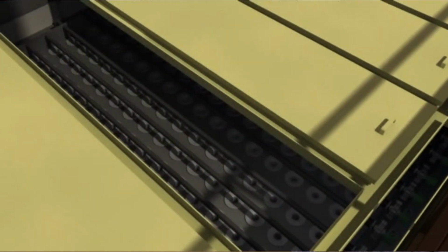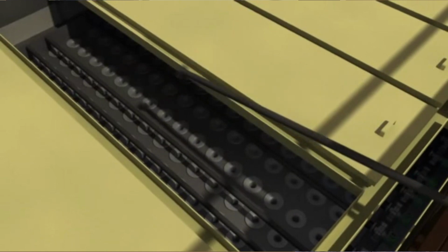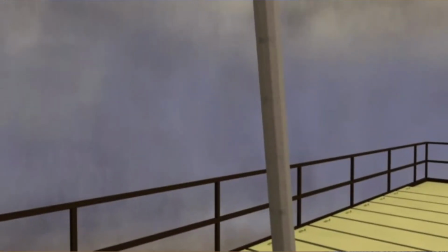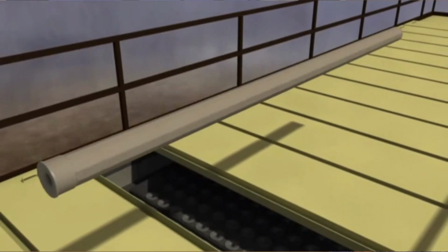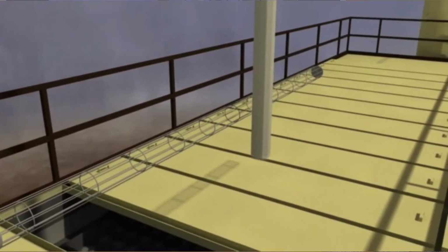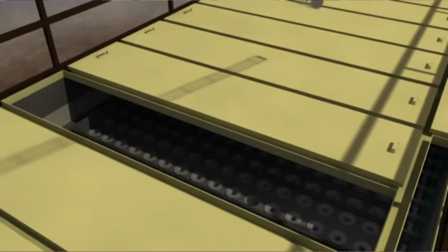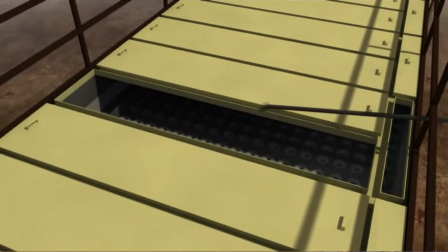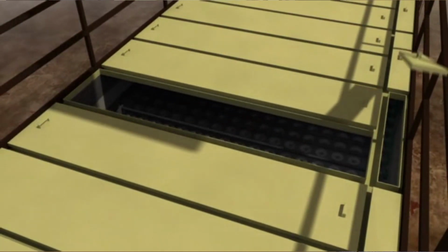Here's another view. If you remove the blowpipe, you can see the bags. This is something you would want to inspect when you're getting ready for a stack test. You want to see if you've got any dust on the top of that tube sheet. Just kind of a quick representation of how you would change a bag. Cage pops in, you would put your blowpipe back into place.